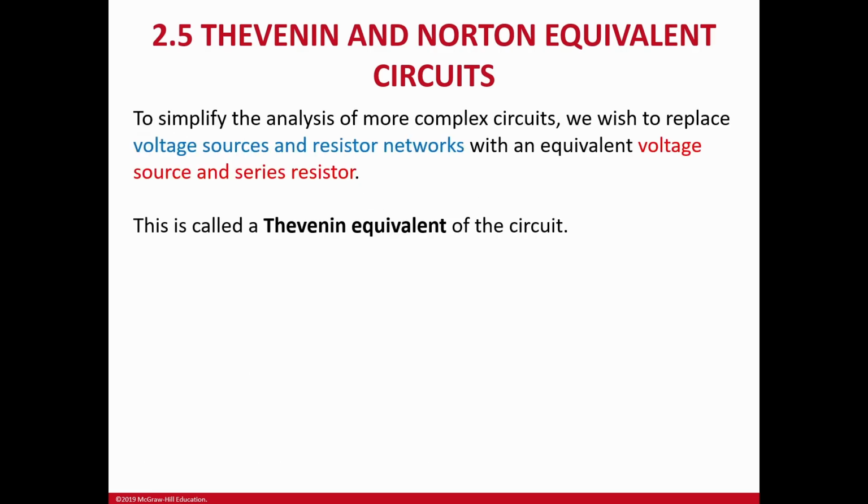The purpose of the Thevenin and Norton equivalent is to simplify your circuit. For example, you have a voltage source and a bunch of resistor networks, that means a complicated resistor network, and you need to simplify it, right? So you replace these complicated ones with a voltage source and a series resistor, and this is the purpose of using a Thevenin equivalent.